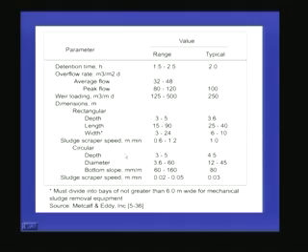It is almost similar to the primary sedimentation tank of water treatment, but here we are assuming it is type 2 settling. So, we cannot use Stokes law for the design of the sedimentation tank of wastewater treatment. And yesterday we talked about many secondary treatments, and we have also seen that in certain secondary treatment units, they do not require a primary treatment at all. For example, oxidation ponds and aerated lagoons, because that system itself will be acting as a primary treatment unit also. Everything will be settling down at the bottom of the tank, and we are giving such a large detention time.